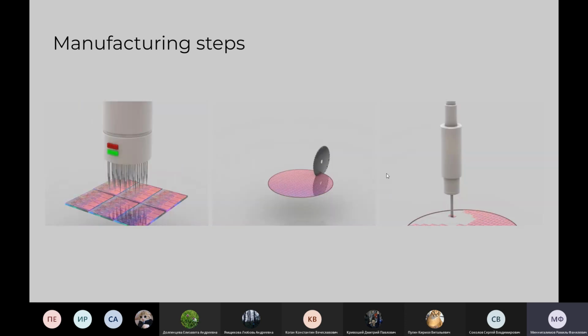multi-level highway system. And finally, a small part of the finished wafer will be put into the first functional test. During this phase, the test sample is applied to each single chip and monitored, comparing the response from each chip. After the test determines that the wafer has good performance in processing devices, it will be cut into pieces called dies. The dies that respond properly to the control patterns will be moved to the next step, packaging, and the bad dies will be removed.